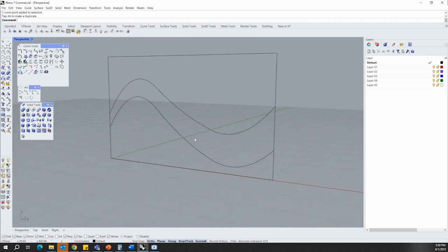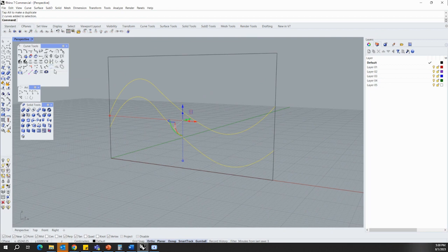So what we have to do right now is create one more curve in between these two curves. The interesting option we can use is twin curves, because copying it won't be the proper mid curve. Twin curves will twin between two curves. It will give this midpoint. We'll take this midpoint as a reference and form a similar curve in between these two curves.